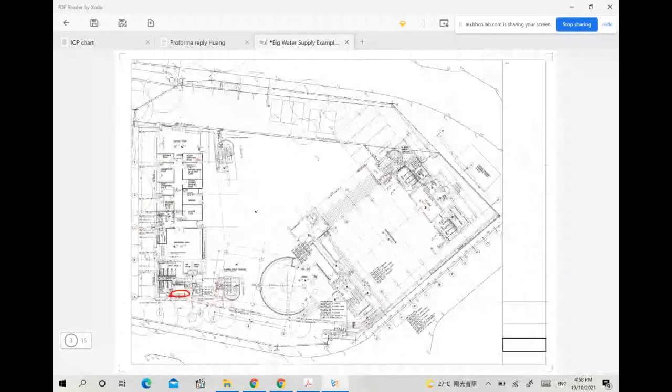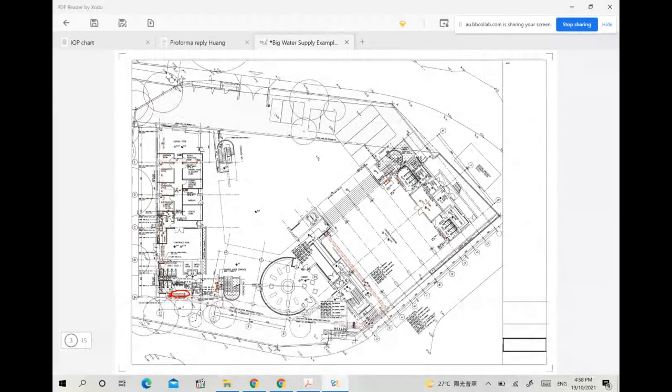Now, I give you hints. 99% of the time, for the pumping and drainage, you are required to prepare one-line drawings only. But for the air conditioning chiller water pipe, maybe its size is over 300 mm, so very big in size. So we may consider using two-line joints, double line joints. That depends on the scale issue.